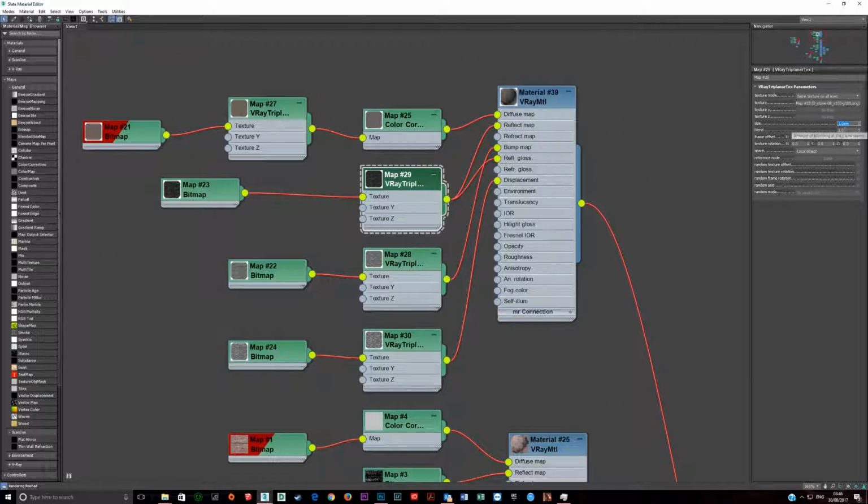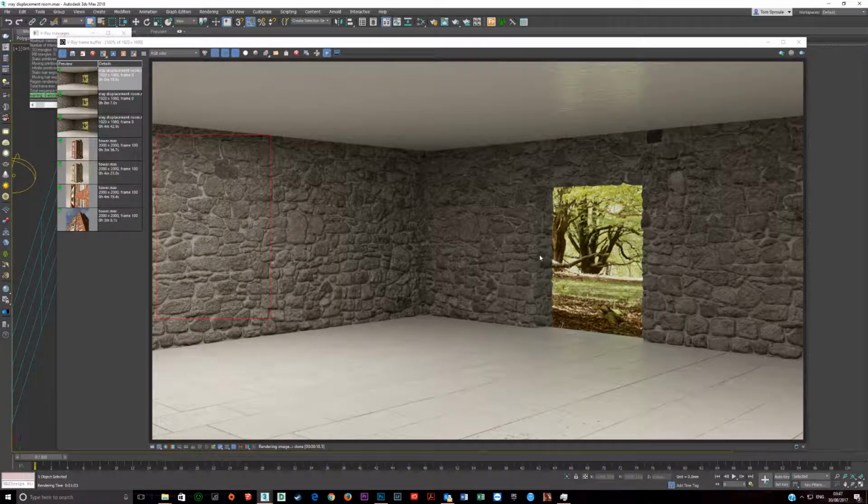And then I've set that blend to 1, because it's a displacement. By default it's 0.1. So I've made that 1. And then these are exactly the same. And all these maps come in through these. And this is the diffuse going in through the same thing as well. The reason I have the triplanar texture is it blends on corners, it blends on curves, which is what you want to be seeing. See here?